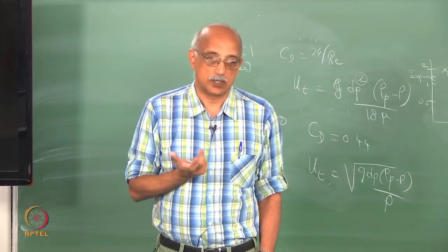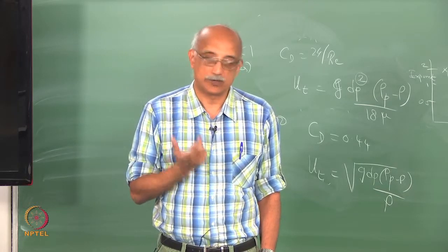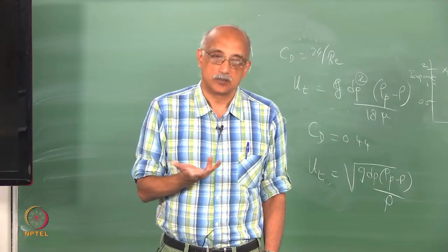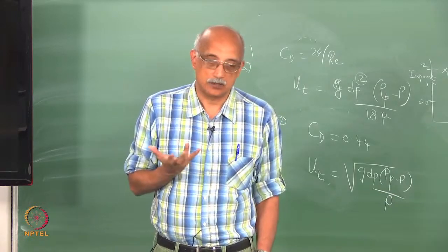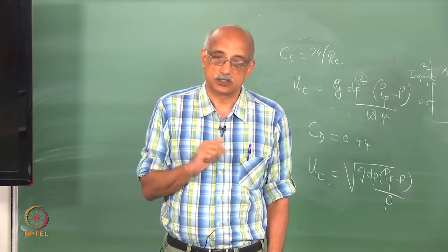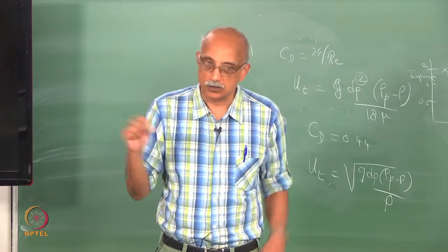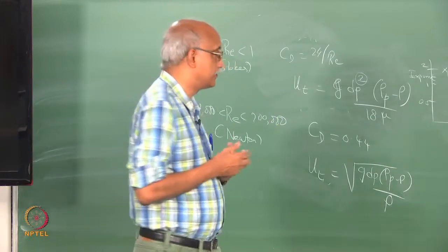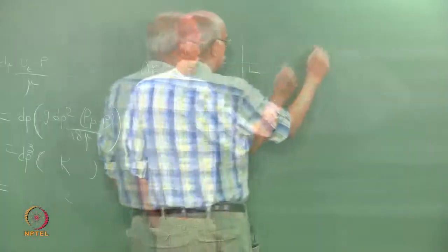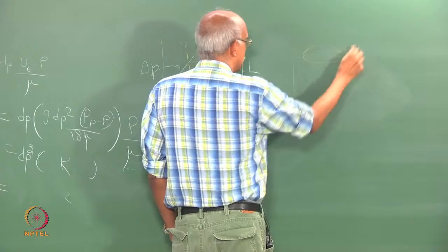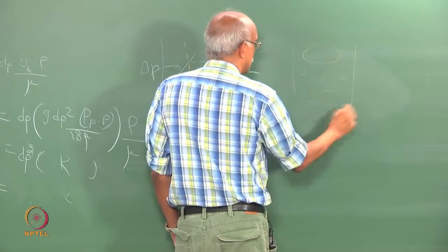A spherical droplet will flow with very different characteristics compared to something that is non-spherical, but you cannot again always say whether the spherical body will move slower or faster, because once you start elongating it or compressing it and you have a non-spherical shape, the key parameter becomes the relative orientation of the droplet or particle or whatever to the general direction of flow.